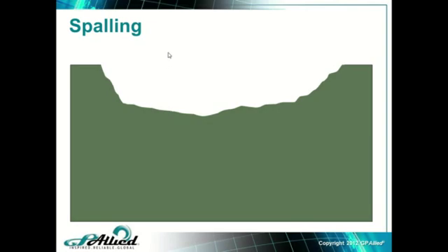Remember, the oil wedge is dependent upon a small contact area. So what do you think happens when this oil wedge comes off this ledge here? The contact area gets much larger, relatively speaking. And it's much more difficult for the lubricant wedge to maintain its shape because the pressure's off, or, you know, a certain degree of pressure is off. So we lose our ability to keep the surfaces separate because we now have a larger contact area. So as the roller's moving along here, it's knocking little asperities off, little chunks off, and then when it hits here, it's a pretty rough ride for it.